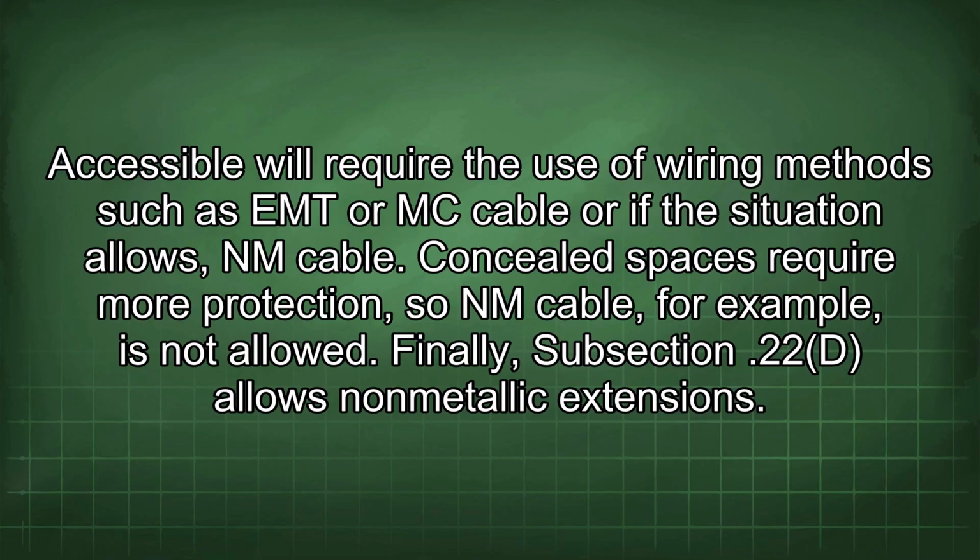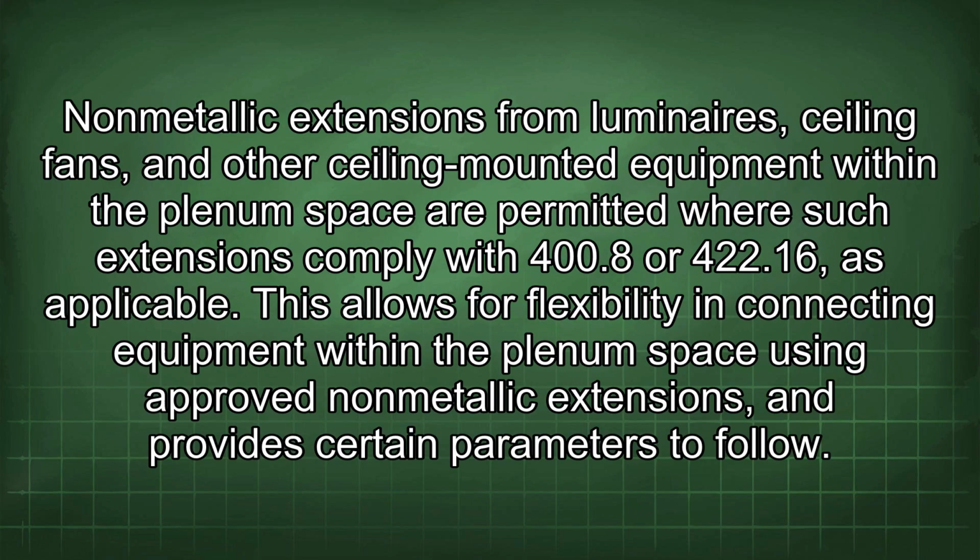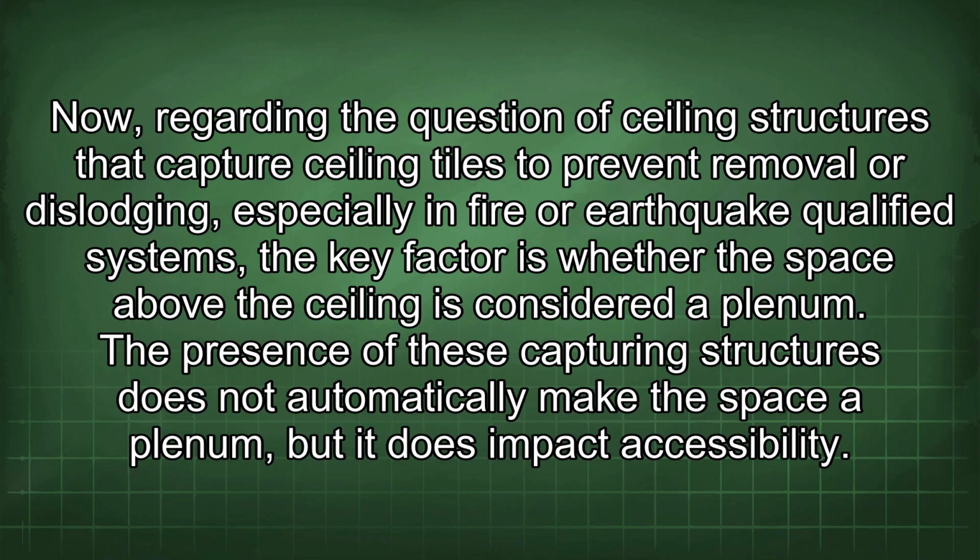Finally, subsection 22d allows non-metallic extensions. Non-metallic extensions from luminaires, ceiling fans, and other ceiling-mounted equipment within the plenum space are permitted where such extensions comply with 400.8 or 422.16 as applicable. This allows for flexibility in connecting equipment within the plenum space using approved non-metallic extensions and provides certain parameters to follow. Now, regarding the question of ceiling structures that capture ceiling tiles to prevent removal or dislodging,